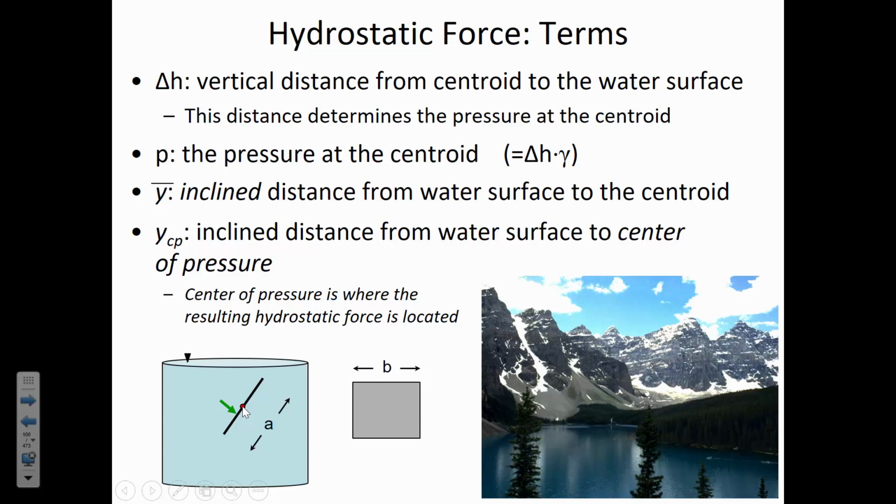Yes? Does the force always act perpendicular to the bottom? Yes. So he's asking about the direction of the force, and it does act perpendicular to the flat plane. When it's a curved surface that the force is acting on, we'll break it up into vertical and horizontal forces. But when it's flat, we'll just say there's one single equivalent force which is acting perpendicular to the orientation of the plate. Other questions?